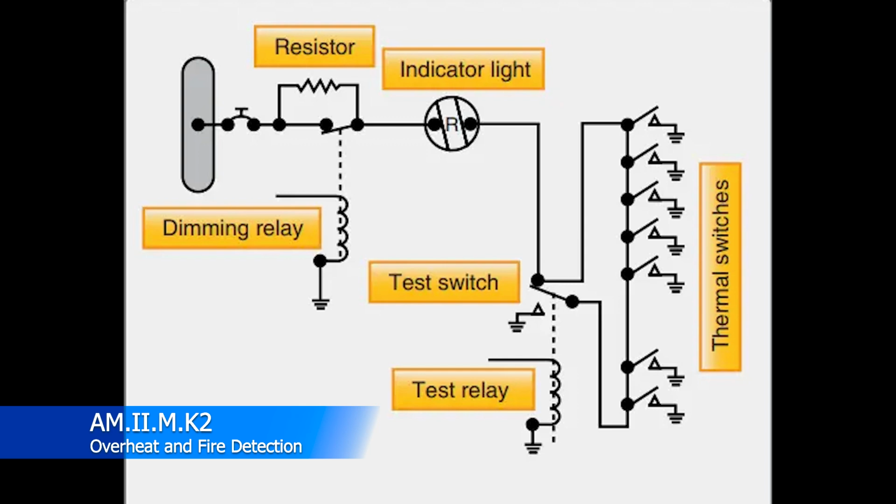Now, the thermal switch is actually pretty common even outside of aviation. Your dryer, for instance, is going to have something very similar to this in it. Thermal switches are just heat-sensitive units that complete electrical circuits at a certain temperature. That's all it really boils down to. So you have the switches there on the right-hand side of the schematic.